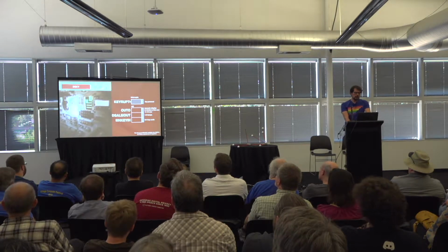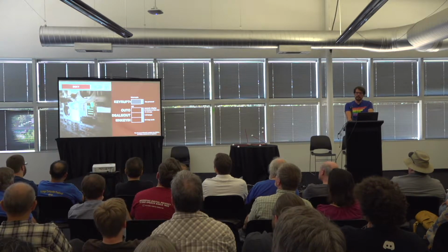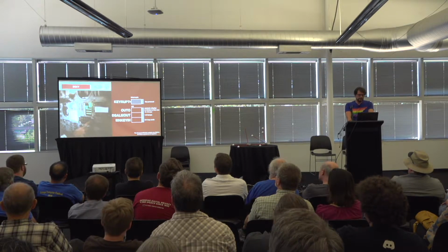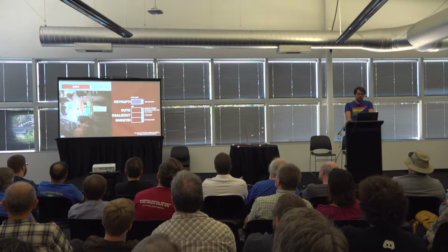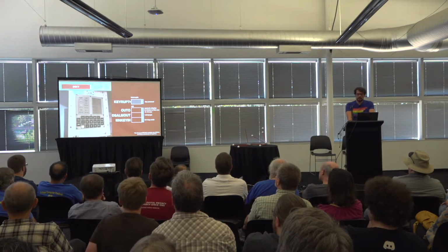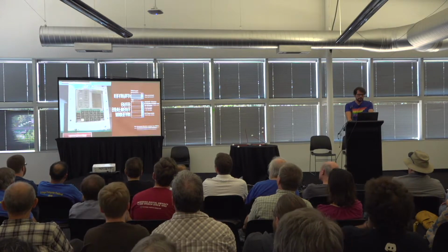The user interface is provided by the so-called DSKY, which stands for Display and Keyboard. It has 19 keys, 15 lamps, and several numeric output lines. Keys generate the KEYRUPT interrupt, and the key number can be read from the key-in I/O channel. The numeric display is driven by the out-0 channel.